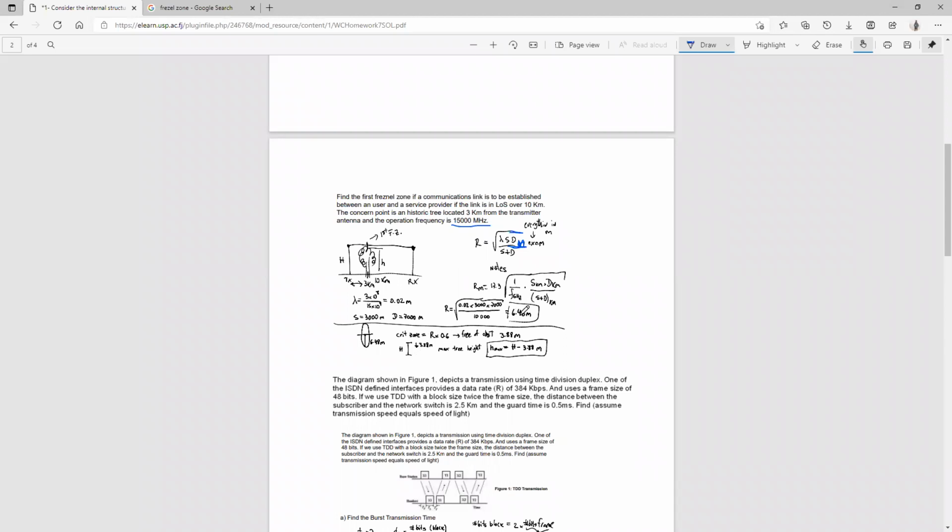So we find 0.6 of the radius. The critical zone is within the first Fresnel zone. We know it can cause errors to the main signal, right? So let's say this tree still falls within the first Fresnel zone, but what should be the height before it is much more critical, before which we cannot ignore the tree at all, right? The critical zone is actually given by r times 0.6. Our radius is 6.48 meters.